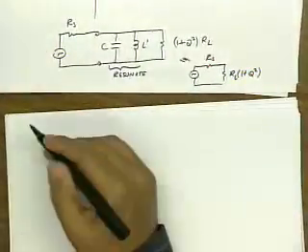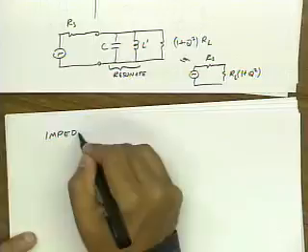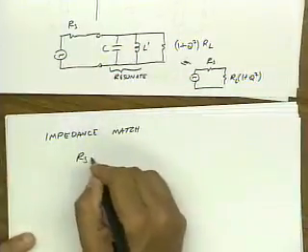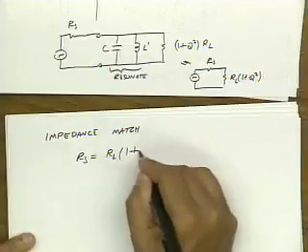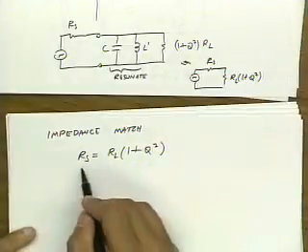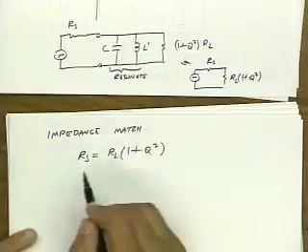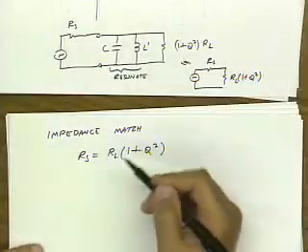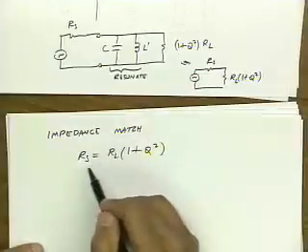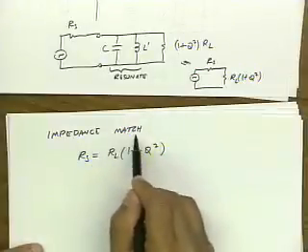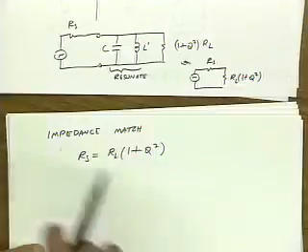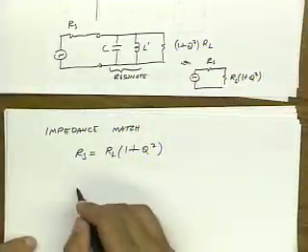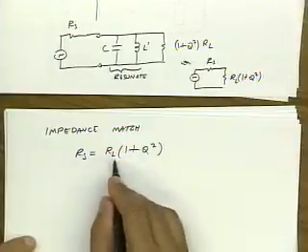So now if I want an impedance match, I would set RS equal to RL (1 plus Q squared). Now this RS may equal the RS of the source, or it may be equal to basically the optimum source impedance or the optimum load, and so on and so forth. So it's not necessarily a match to the same impedance, it's a match to the impedance that you'd like to see. Okay? So if I solve this equation, remember RS and RL are usually given.